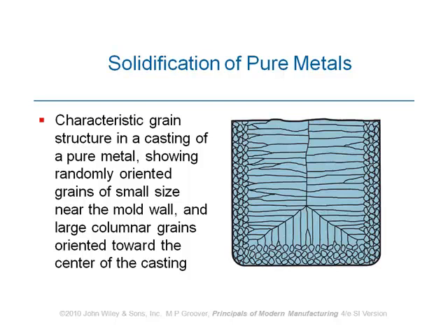Meaning that the atoms sitting here are still hot, and eventually they arrange themselves in the crystal structure which has started from the external surface. The growth direction is inward, and from here as well, you can see it's inward. And this is the hot region inside. So what we get inside the material is not a unique microstructure.